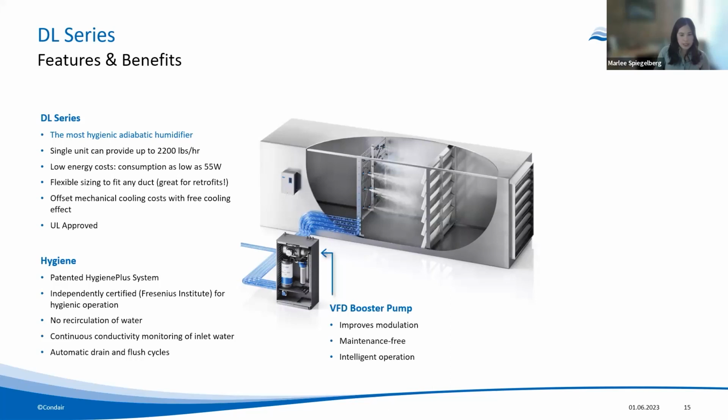The DL type A system, which is our standard system, also has a VFD booster pump. This pump improves modulation by boosting the supply pressure to the ideal operating pressure of about 7 bar. This allows for fine control up to that 2%.